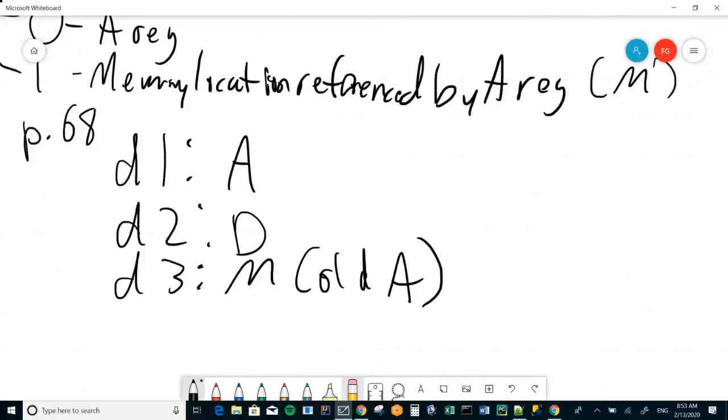By saying something like A equals M, we're able to say whatever that location is, just stuff that value straight into the A register, and now it's pointing at that. That can be really handy. So this is really useful stuff when thinking about this architecture.